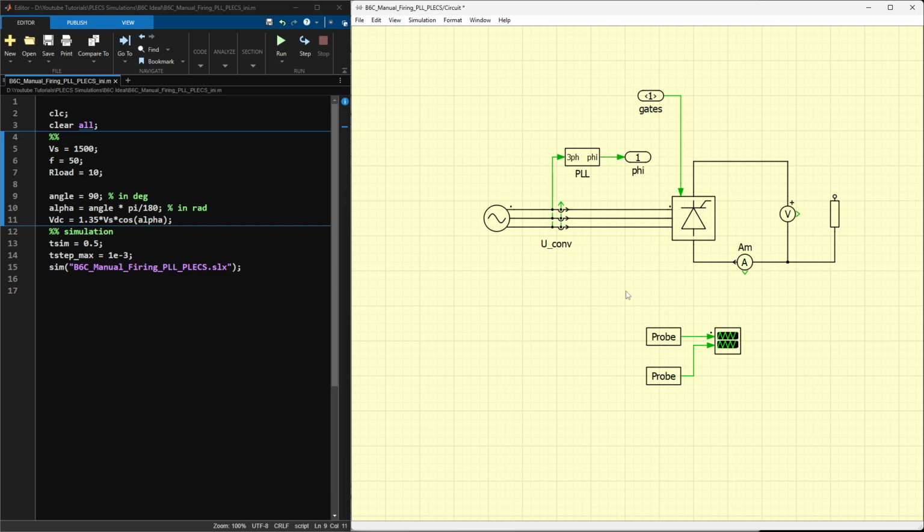This may not be the case, as we won't always have an open circuit voltage here. We will almost always have a load connected there, so we need to find a way to match the real operating conditions. The continuity of current has to be ensured on the output side, so that we can match our theoretical calculation to the simulation. Let's take an inductor and connect it to the DC side.